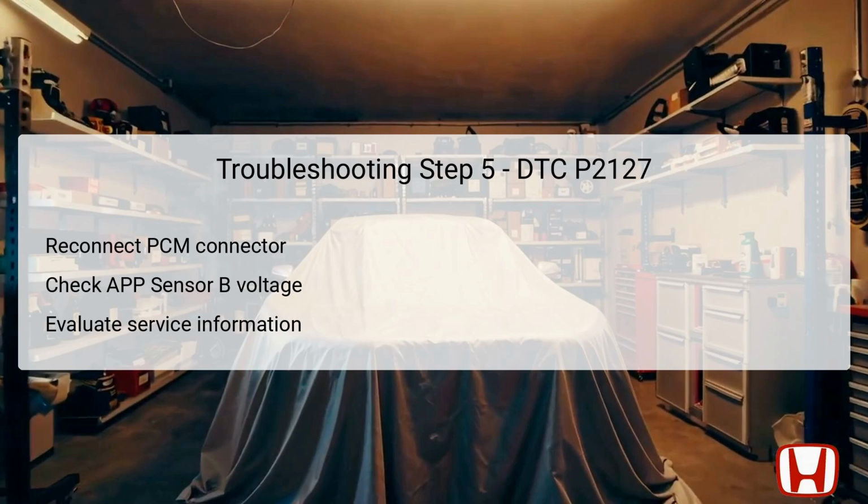If the conditions match, you will then consult authorized service information to assess the DTCs or symptoms you are troubleshooting. It is also prudent to substitute a known good PCM and see if the DTC P2127 clears. If it does, then replacing the original PCM is recommended.